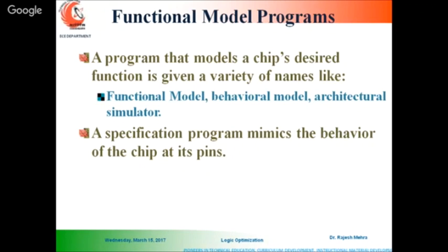As I told you, we have two kinds of ASIPs, application specific processors. One is your microcontroller, another one is DSP. Because both these cannot be optimized together, that is why we have two different processors with us. Whenever you are dealing with control kind of applications, we always use microcontrollers. Whenever we are dealing with data flow kind of applications, we always use DSPs, right? So yes, if you want both, then you have to combine them, and you have to go for what? You have to go for ASIC kind of design. You have to develop your own ASIC.